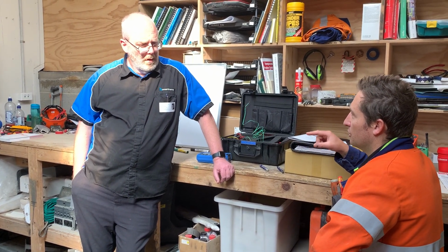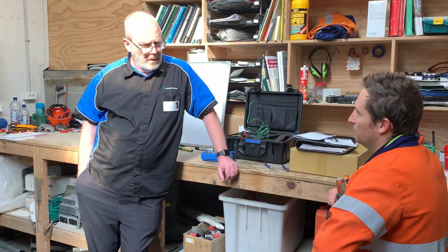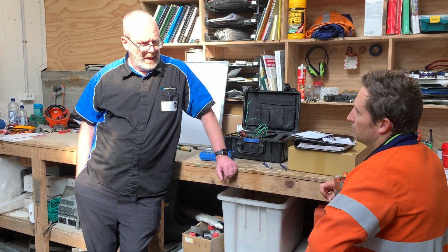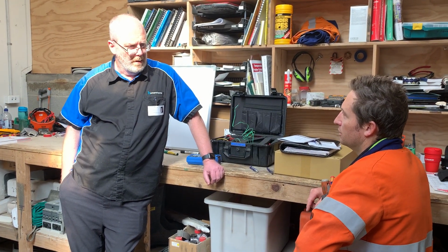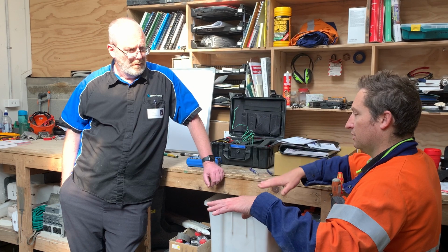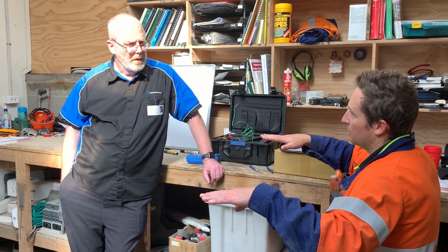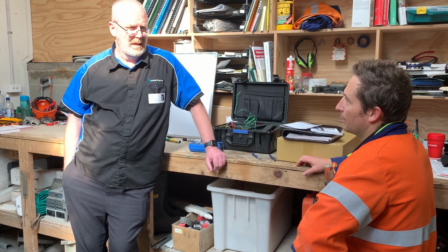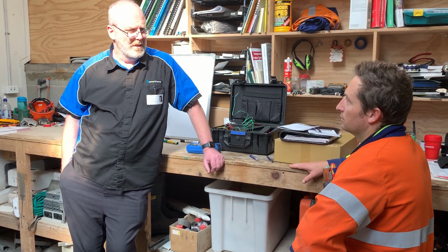Now, as the ambient temperature of the room rises, what happens to my temperature? It won't affect it. It will automatically compensate. So as the temperature fluctuates ambiently, the reading should be stable? Correct, it should have no effect at all, because electronically there's a sensor that says ambient is this, so I'll make the cold junction move by this amount. Correct.